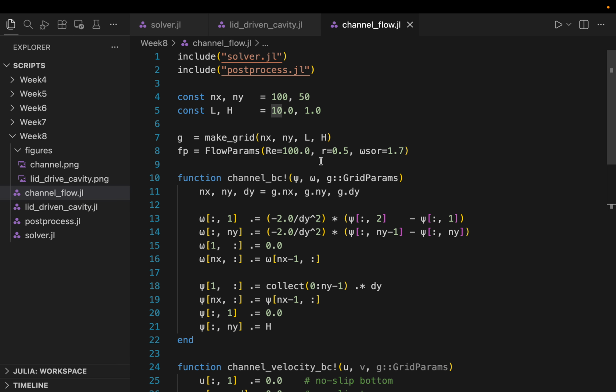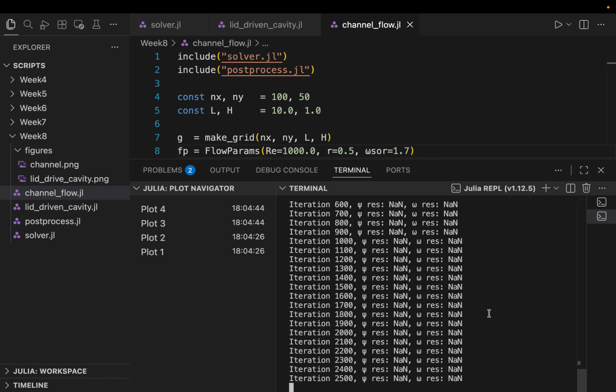So this is again for a Reynolds number of around 100 or something. If I keep a very high value of Reynolds number, then this might not work. So what would be the reason that it will not work? Per se, I give a Reynolds number here of, say, turbulent. This is a channel flow, so it's around 2000 or something. Let's say I give around 1000 or something, and let's say it didn't converge.